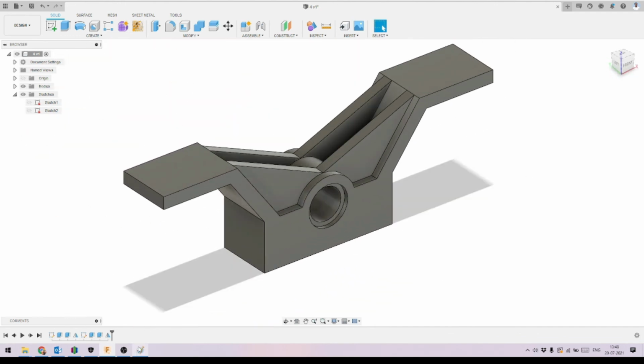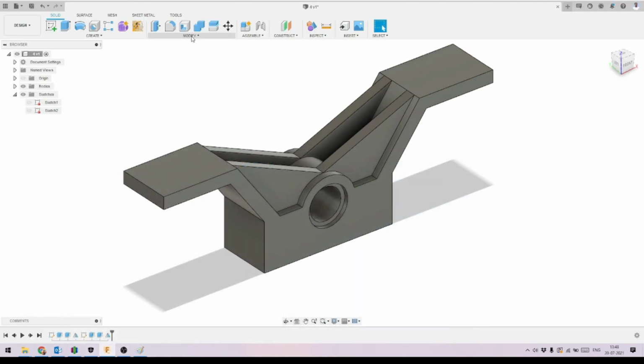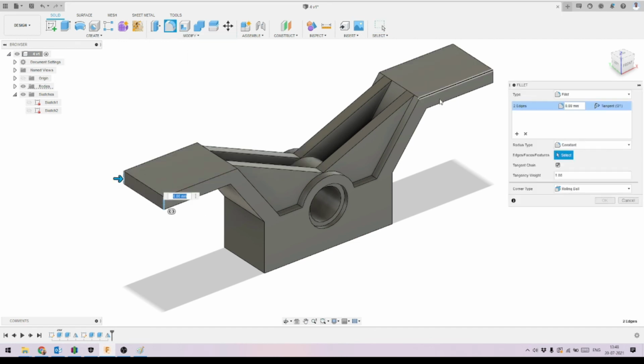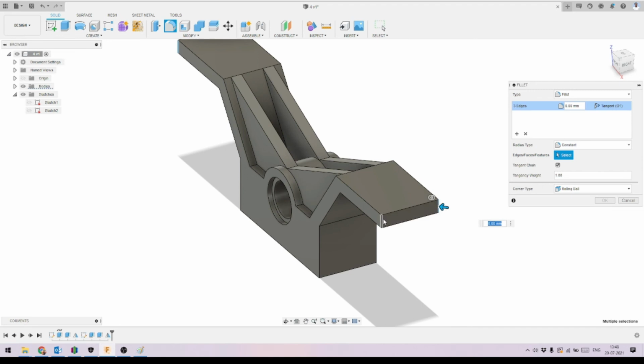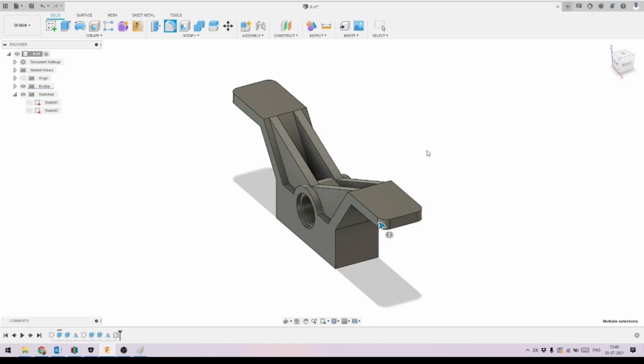And here you can see now we only have left to make these corners fillet, and we have to create these holes. So these are just simple operations, so we can do it quickly. Here you can see the fillets are 3.125 on all four corners. So we can go to modify, activate the fillet tool, and select all the four corners at once. Here you can see all four edges are selected. We can just apply the fillet measurement here, 3.125, and press OK to get it done.